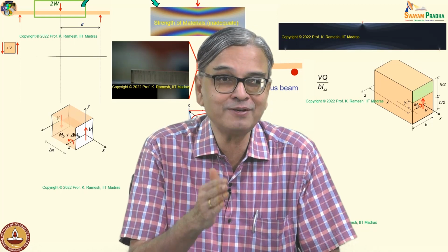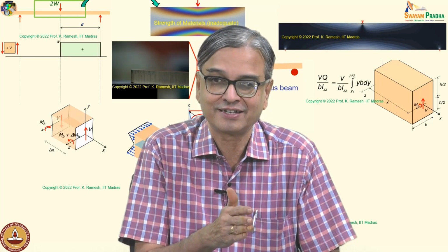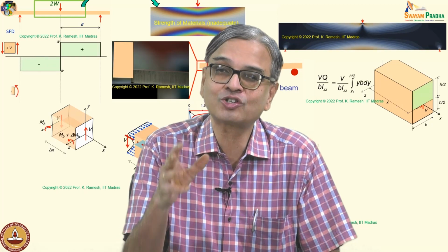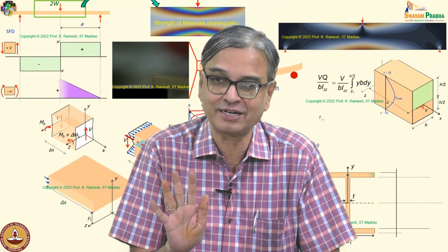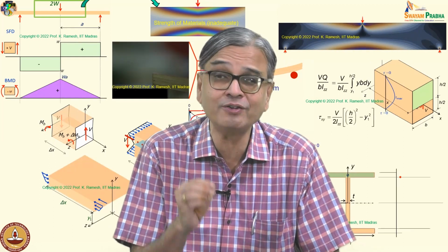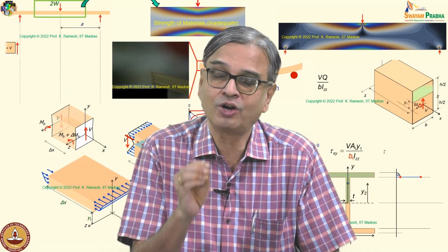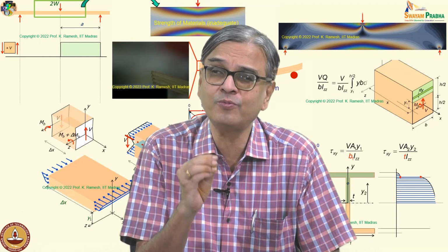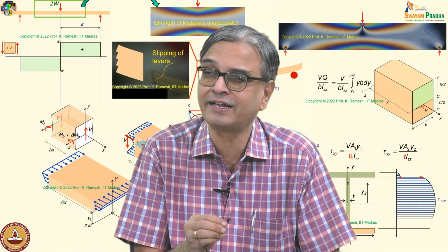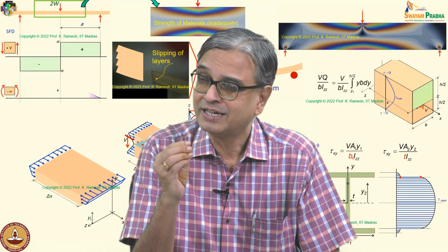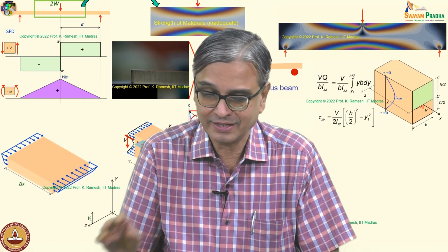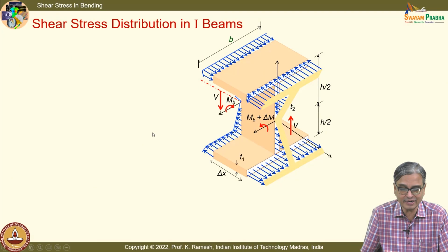That was applicable for a rectangular cross section or any closed cross section. When you take a vertical cut, you can do that. When I have an open section, you have to investigate the problem afresh. So, you have to go back to the fundamentals, how we have started calculating the shear stress distribution. So, I am going to make a vertical cut.